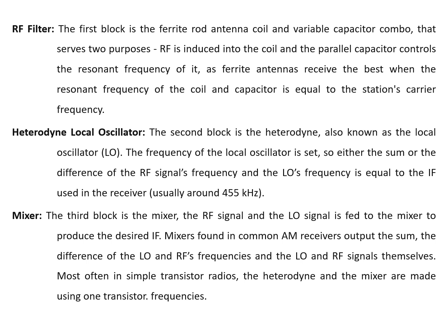Then we have a heterodyne local oscillator. This is the second block, and here we are going to talk about the mixing, that is, the input frequency from RF and the output from the local oscillator. So here we are mixing, which is why it is called the heterodyne local oscillator. Here the IF frequency we are using is around 445 kilohertz.